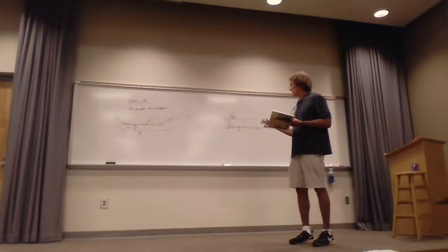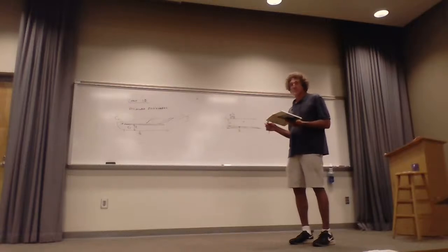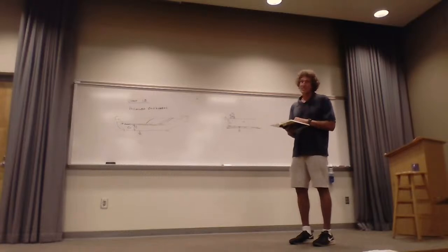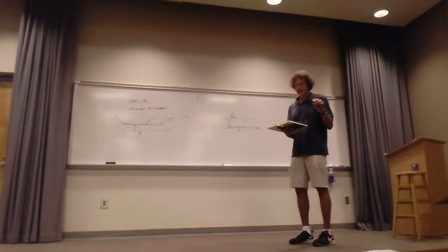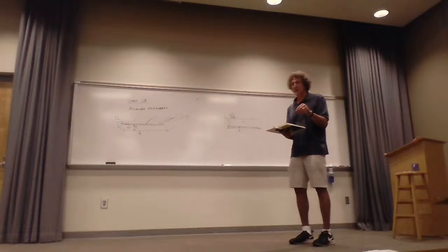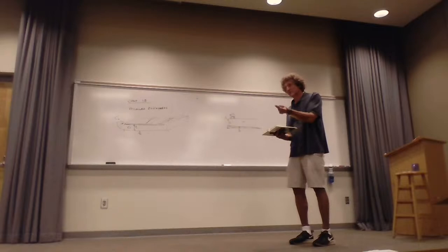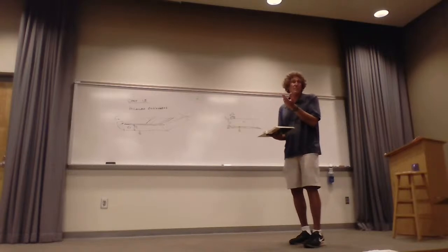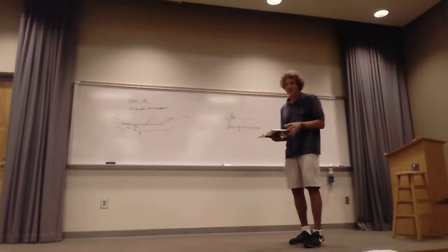And I learned a lot about how all those formulas in Stu's book and other books aren't really used. You know how people do it in the real world? They have a little tool and they just go in, and you don't go through the design work yourself. If you want some parameters as far as the geometry of devices, you put in the characteristic impedance you want, you put in the constraints, the epsilon relative, and you can pick W or pick the thickness, and bang, it'll find all the other values that you need. And that's what's really done. That's the reason I don't spend any time on it, all right?